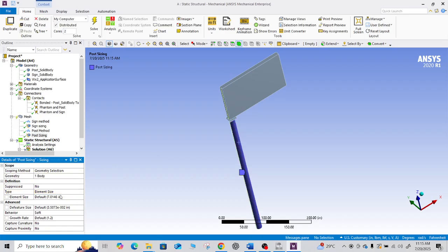The smaller the element size, the finer the mesh is. So if you decrease the element size, the computational power you need is higher, so it will need more time to solve. Okay, so it has some kind of pros and cons. And if you have, you know, 7, 10 or something higher, then it will take less time to solve. So it's up to you.